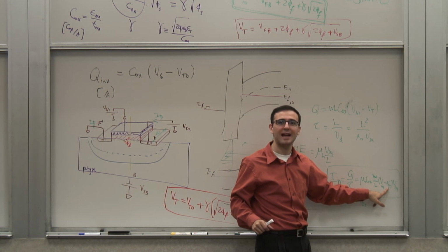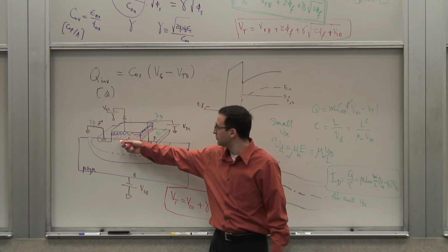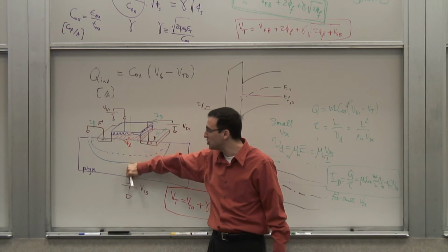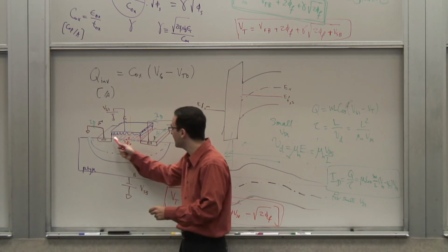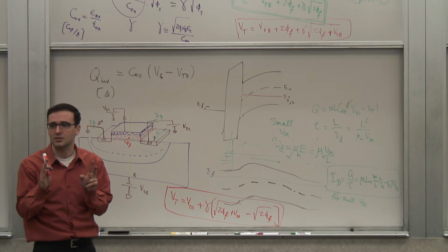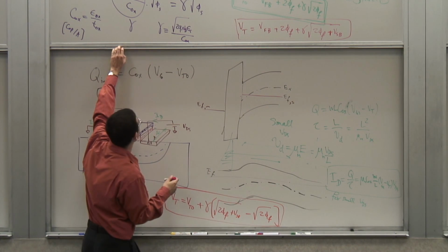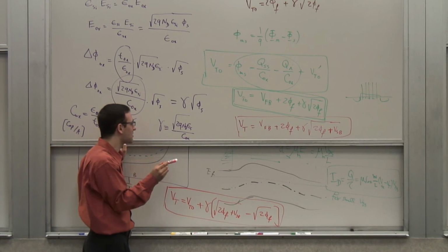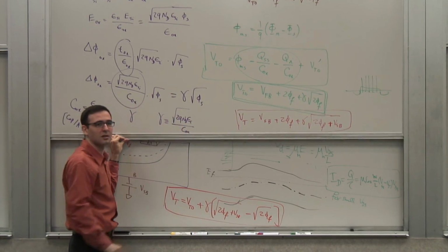And that's why I said I really have two transistors in a MOSFET. I have the original surface MOSFET, and then I have the backgate, which behaves like a JFET. Because they're in parallel, they share the same drain and source, but there are two transistors involved. And that is consistent with this picture. The ratio of the strengths of these two transistors is the ratio of the depletion capacitance to the oxide capacitance.